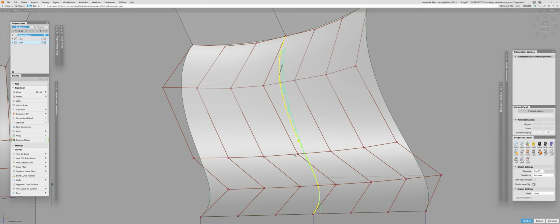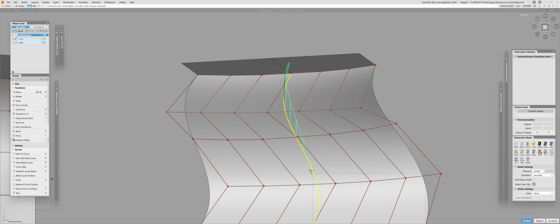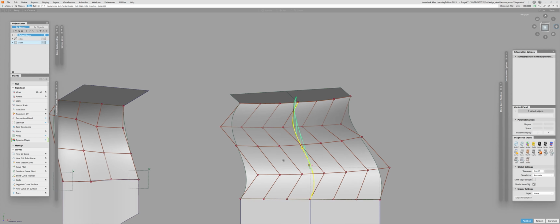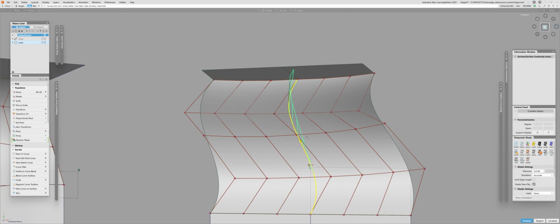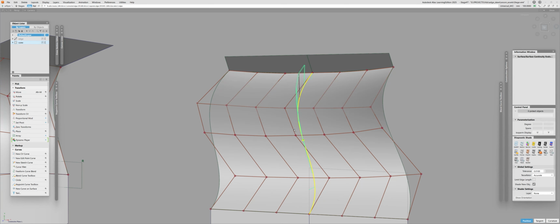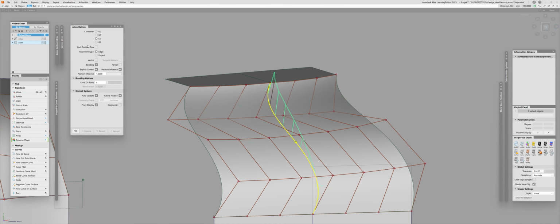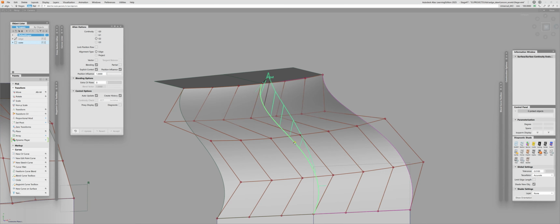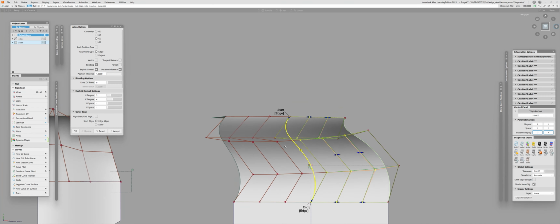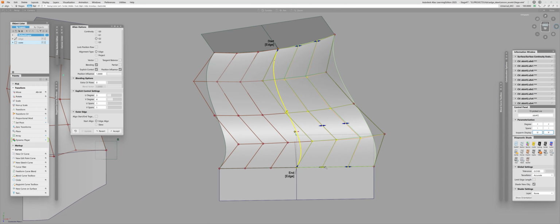Now, if you watched my video about the cross-align method, then you know that the proper way of doing that is to create a slab and then use the alignment, aligning these two through the third surface. If you're interested, I will put the link to this method in the description as well. But as this is not the topic of alignment operations, let me just quickly align one to another and call it a day. Like this. Now I have some curvature deviation, and the reason for that is probably not enough space.